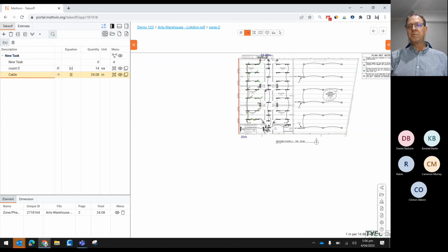But at the moment, we've only measured that in plan, and there would be a drop down at each switch. So for every length measure, we want to add 2 meters to allow for the additional length from the wall down to the switch, double that to 4, to be honest.